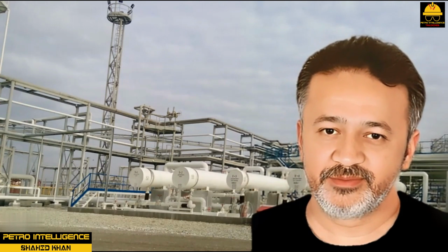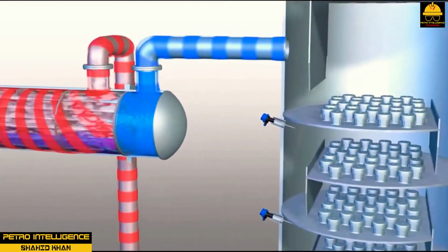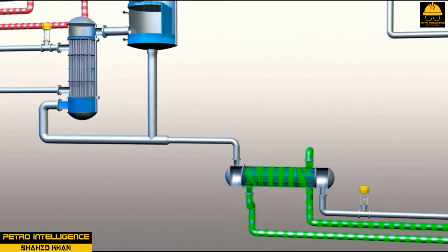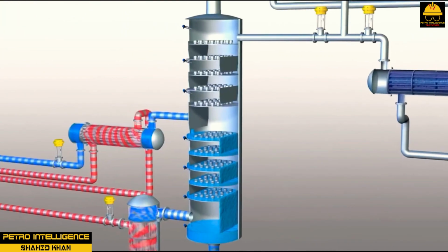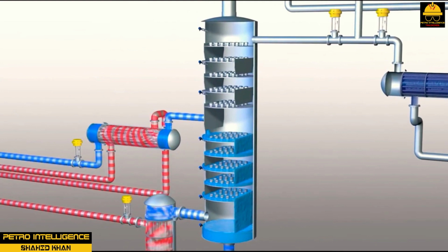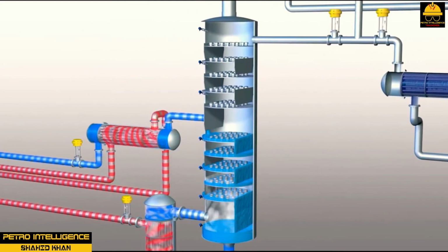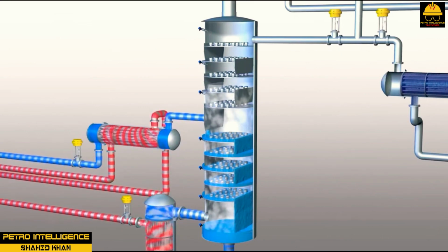Distillation columns. Distillation columns use heat exchangers to preheat feedstock in a heat exchanger, condense hot vapors in a condenser, or add heat to the tower and crack or separate heavier components in kettle and thermosiphon reboilers. Condensers are typically shell and tube heat exchangers used to condense hot vapors into liquid. A condenser can be found at the top of most distillation columns.